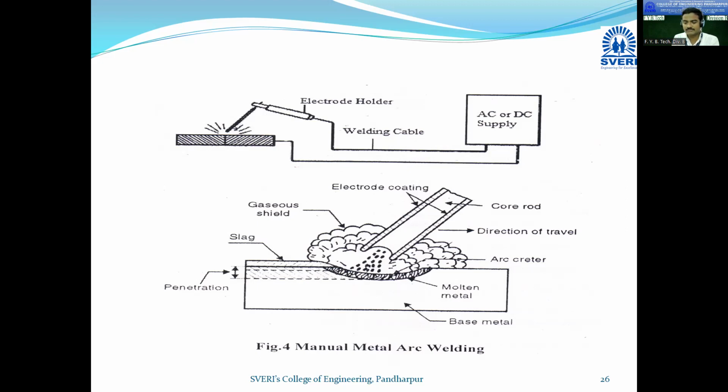And once welding is completed, we have to keep it for solidification. Solidification means you keep it in the air for effective cooling. Sometimes we spray water over the welding. If you spray water over the welding, the required strength will not be achieved. What happens is that after a few days it breaks and cracks soon. But when you put that welded part in the atmosphere, we can obtain a good life for that welding.